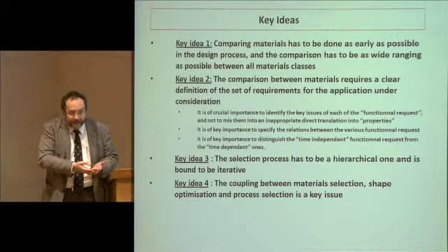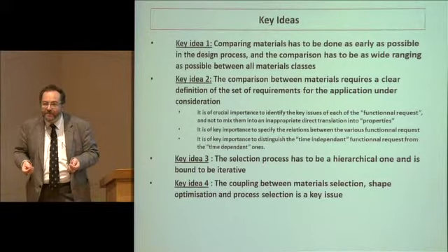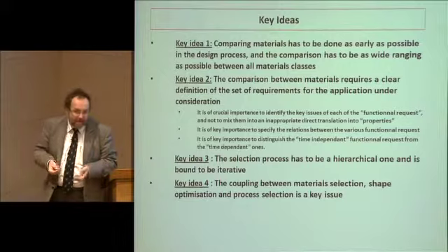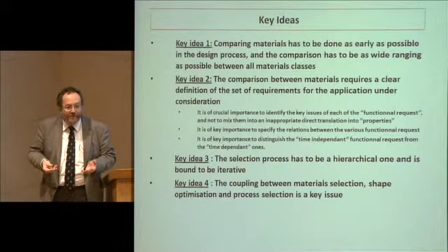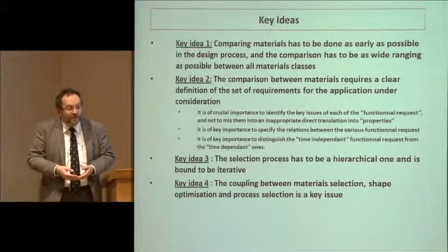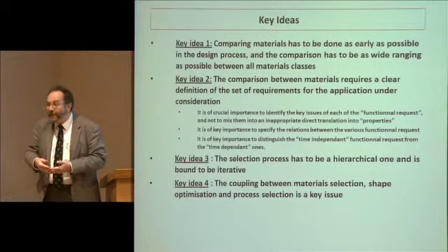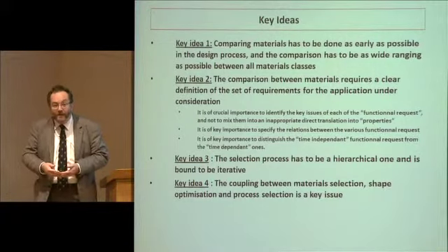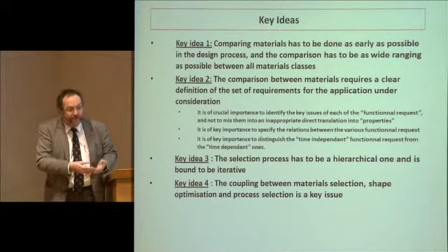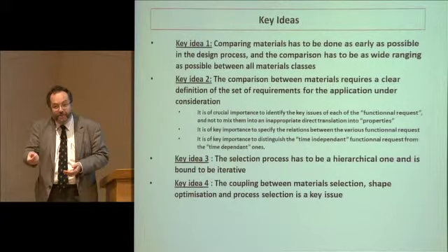So if you come along and ask someone to make an alloy wheel out of steel along the same model, it won't work because it can't be cast. So the question of knowing whether you're going to be using steel or aluminium makes no sense if you don't ask at the same time how you're going to make it and what shape it's going to have.